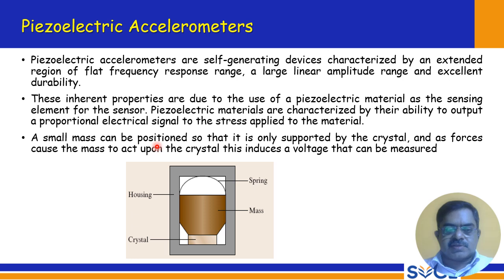A small mass can be positioned so that it is only supported by the crystal, and as forces cause the mass to act upon the crystal, this induces a voltage that can be measured. So that is from the piezoelectric crystal. It is an active type of sensor, piezoelectric material or crystal.